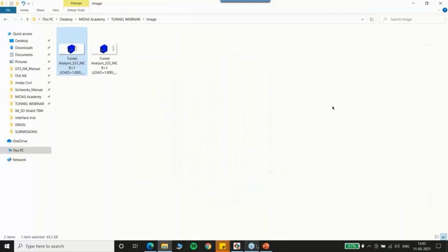And before I close, I got a really good question: how are hydrostatic pressure and surcharge applied over the model? Actually, here we have not applied any hydrostatic pressure, but if you want to do that, you can just simulate the groundwater level. I'll just show you the easiest way of doing it. I'll go to the model right away, and I go to the pre-stage.